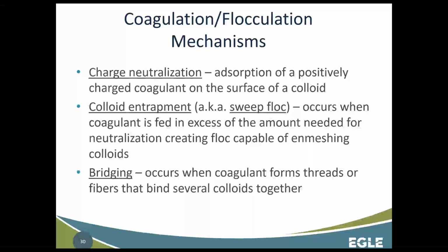You know, we're mixing the floc gently after we've conditioned the particles because we want the collisions, but we have to be careful because if there's too much mixing, the floc that we've worked so hard to form can be broken up. So if the mixing energy is too high in your floc basin, you can end up breaking apart that floc. And that's why generally when you're looking at a flocculation basin, you're going to see the mixing velocity decrease as you move through the basin.